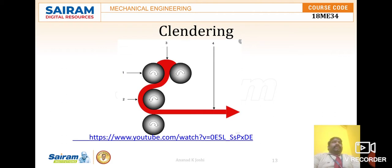This product is then cooled by passing through the cooling rollers, and then may be rolled up as desired. The gap between the heated rollers influences the thickness of the product, while the temperature and speed of the rollers influence the luster and finish of the product.